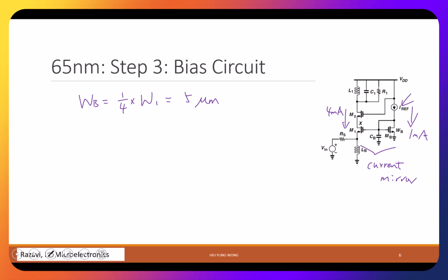Always try to check when you start doing simulation, right? In your calculation, of course, you make sure it is in saturation. But once you do simulation, channel length modulation or some secondary effect can bring you into linear. And whenever you see something that doesn't make sense, like my hand calculation shows this should be that, but why is it not the case? For example, you think this should be about 1 to 4. Even with channel length modulation, it should not be 1 to 10. So either you put something wrong or this was in linear mode already. That's why you don't have the current mirror effect, right? So remind yourself about this.